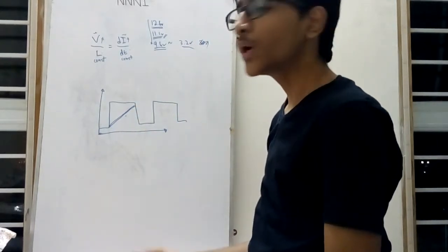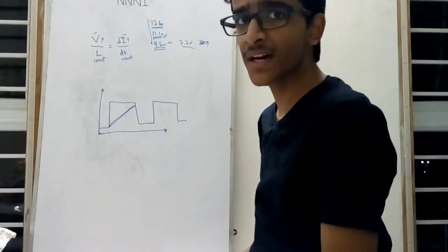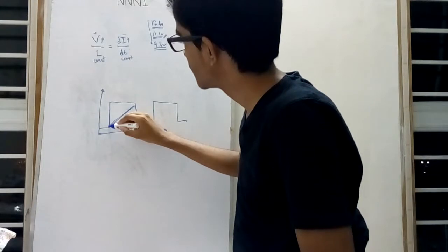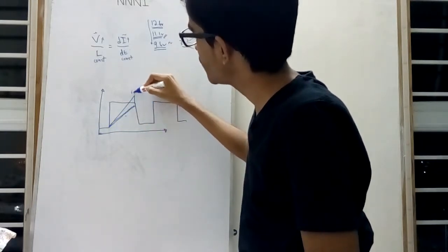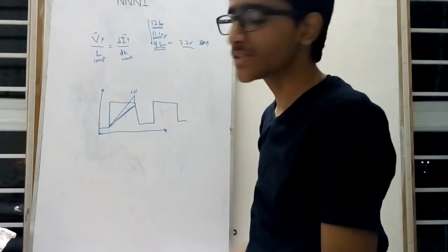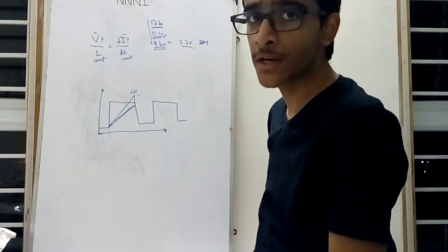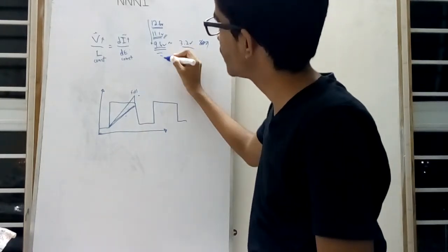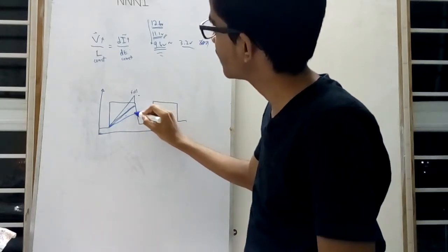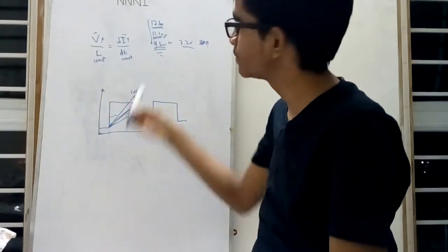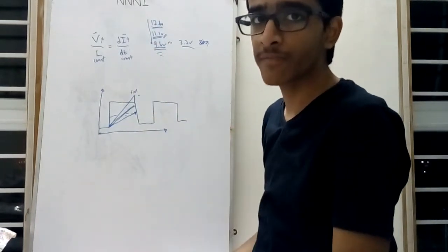But what happens when your voltage drops or you're using a fully charged battery? Obviously the current is going to rise faster. So when the battery voltage is full, you have a faster rise in current. For the same switching time period, you get more current into the primary coil than you originally intended. And the opposite thing with the fully drained state. The current rise is extremely slow, so you have a current less than the current that you desired, or rather calculated at 11.1 volts. And this is the problem I've been trying to solve.